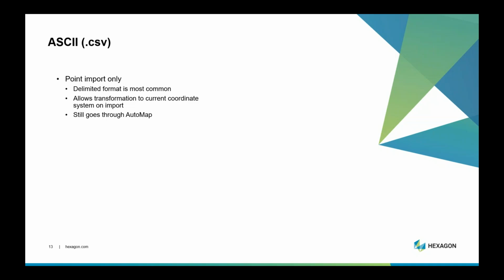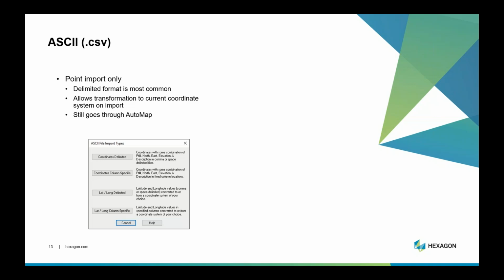This is point import only. It doesn't include any of that measurement data. And the delimited format is going to be the most common format. We have 4 different formats. That'd be coordinates delimited and the lat long delimited are going to be typically the way you'll go.